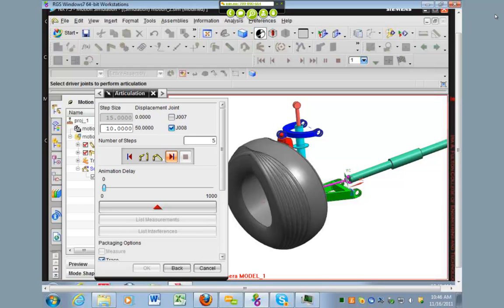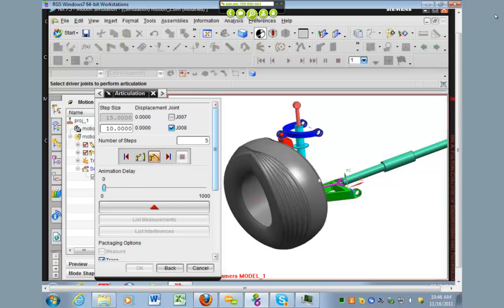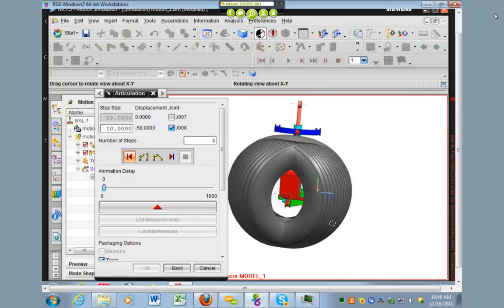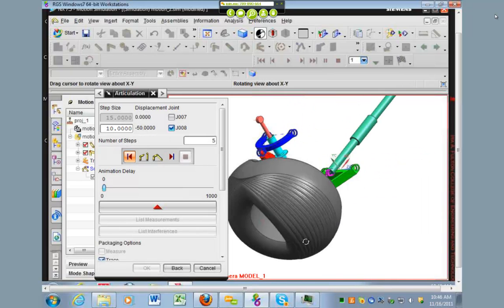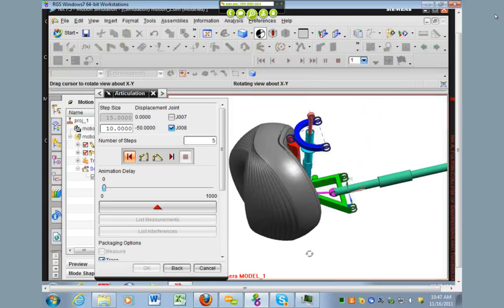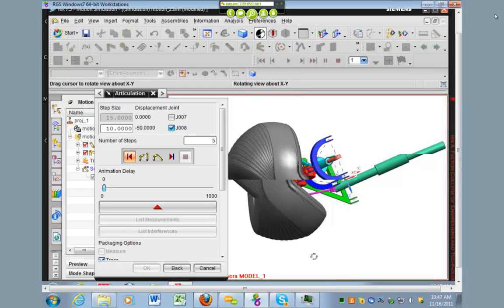So now if we click on assembly position, it'll snap back to the original position without retracing them. And if we trace backwards, it'll make 5 more that way. So now we have several copies of this tire on layer 5 that shows how far it moves, right?